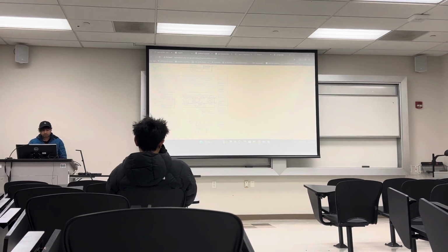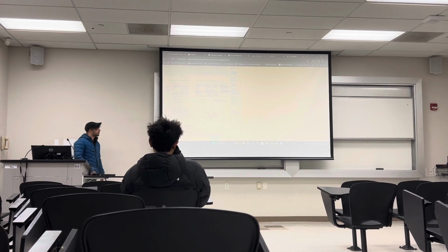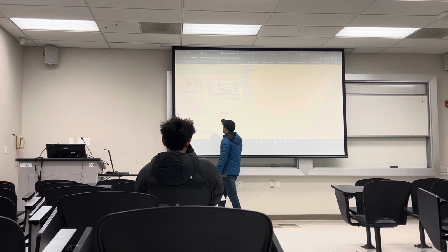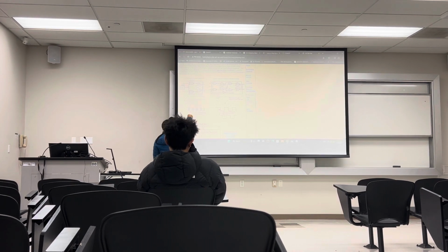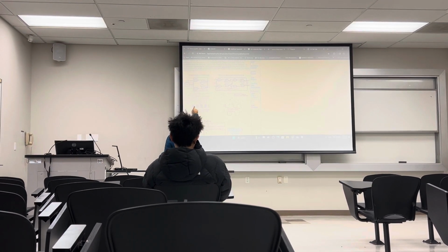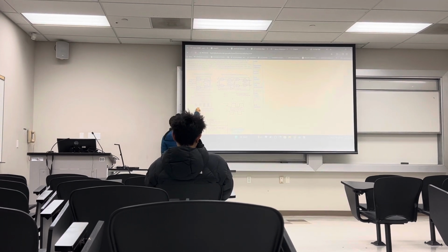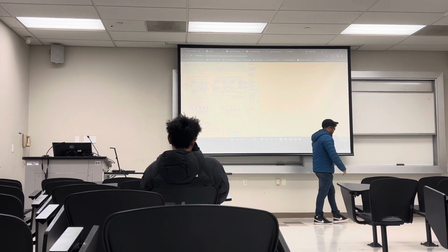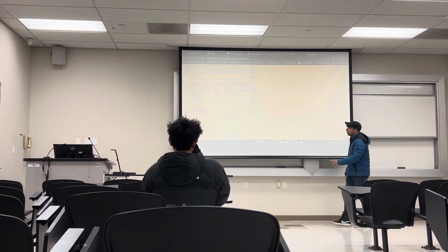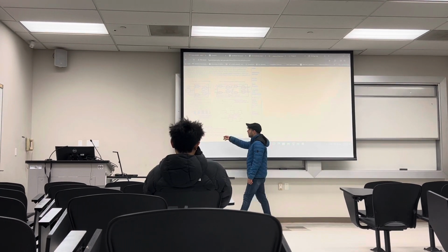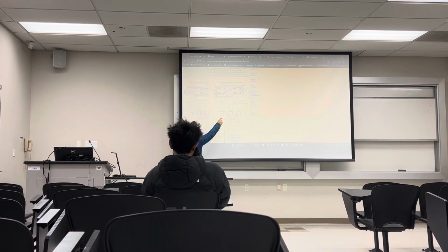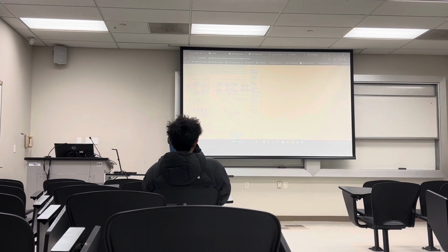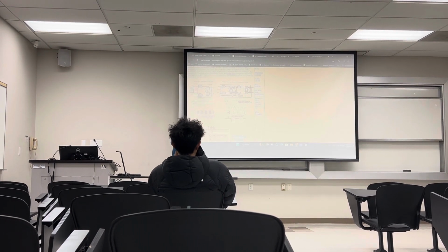First, there are 2 structures for a JK flip-flop. As you will see, there is a simple structure and also a master-slave structure. You can design both, but with the single structure of the JK flip-flop, you have toggling problems. When the clock changes, the output will be set to one value at a single time. If you design that circuit, you will lose some points because of this. So it's better to use a JK flip-flop with a master-slave structure. By designing this one, you will not face this problem, and you can get a full mark.